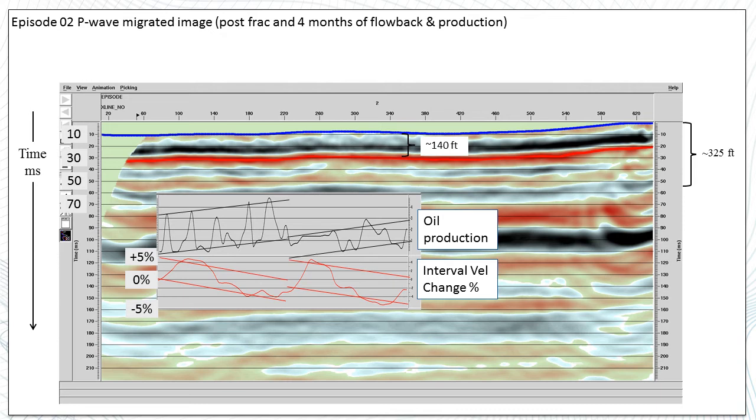Now, interestingly, the black curve above the red ones is oil production, in barrels of oil per day, that was measured, again, using a DAS cable. The DAS cable can passively listen to fluids moving into the borehole, and it can determine what kinds of fluids there are. Well, it's either oil or oil and gas. There's no water produced in this field.